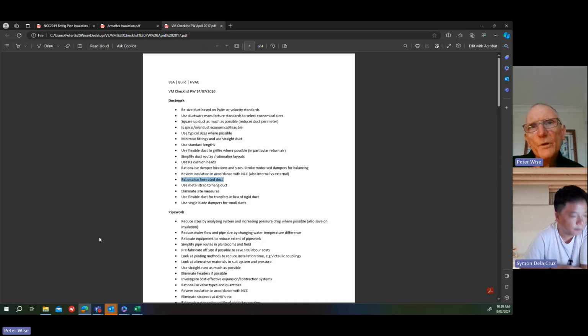With fire wrap, I suppose they can pre-insulate it on the ground, but they still have to seal the joint. So when they put the duct together, they'd have to go back over that. They're more likely to install the ductwork and then put the wrap on afterwards, where they can do the whole thing. The thickness of the wrap, from memory, I think is about 50 millimeters.